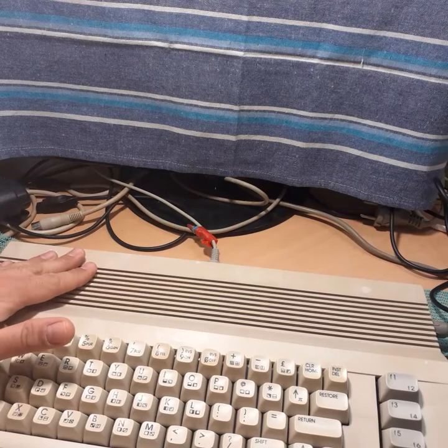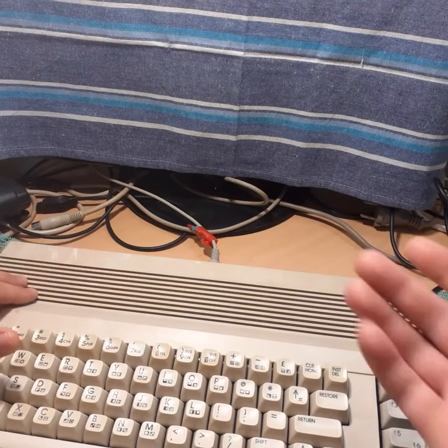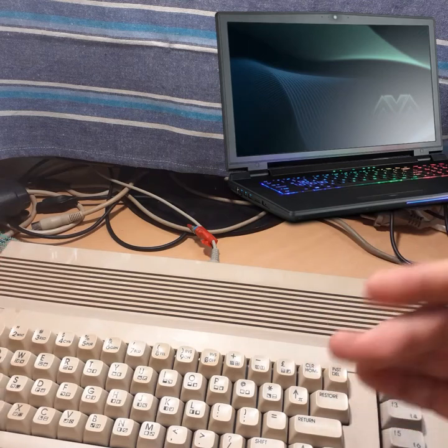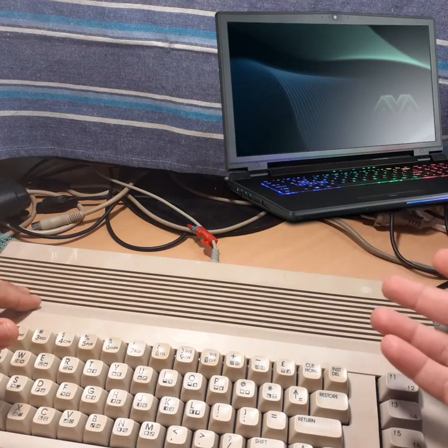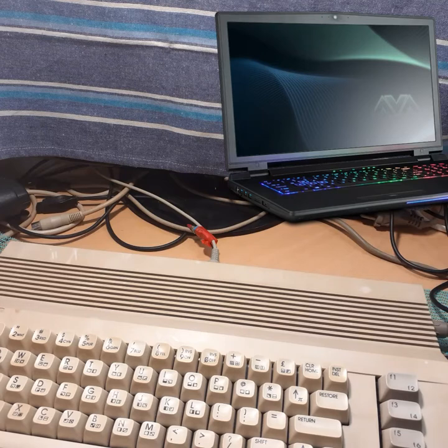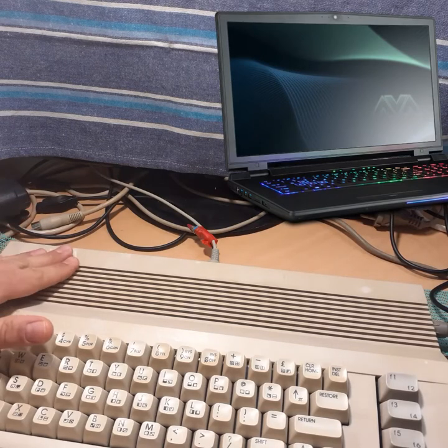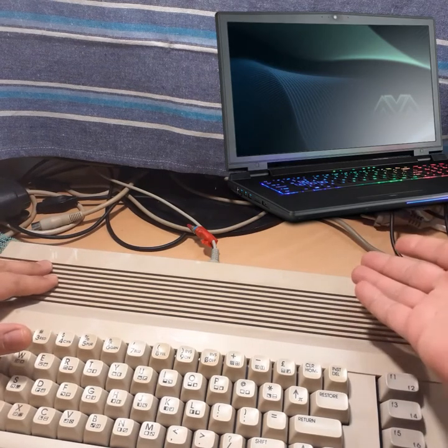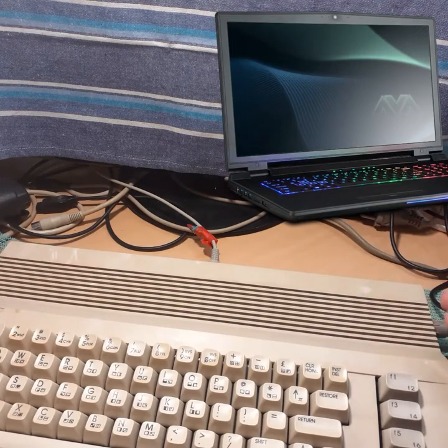Okay, we have a TTL serial communication here, and on a modern PC or laptop we can be pretty sure that we have a USB connector. And as we know, USB devices can identify themselves as a specific device, like a keyboard, mouse, printer, and so on. So that is why we replaced all different kinds of connectors and protocols that we used to have on the PC with just USB connectors. So that is very useful. So 0 to 5 volts here on TTL, 0 to 5 volts here on the USB connection. So we are on the same voltage levels.